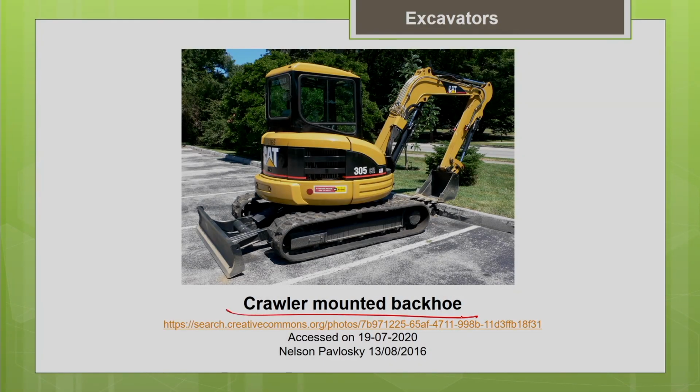That is why for deeper excavations, they put a ramp and bring the hauling unit onto the floor of the pit, so that the bucket will be above the truck. It will be easy to dump the material into the truck. So this is a crawler mounted backhoe, a smaller one. Like this, different models are available. When you are working in a narrow space or confined areas, you can go for the smaller size backhoe. It also has an attachment of a grader, you can see, for grading.